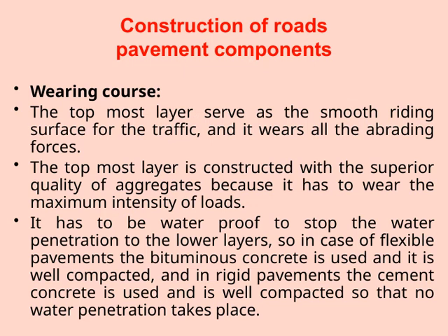The wearing course is the topmost layer of the pavement, and its main job is to provide a smooth riding surface for the traffic. Because it bears the brunt of all the abrading forces from vehicles, it needs to be highly durable. That's why we construct this layer with superior quality aggregates. These are the best materials to withstand the maximum loads and wear over time. Another crucial aspect of this layer is waterproofing.